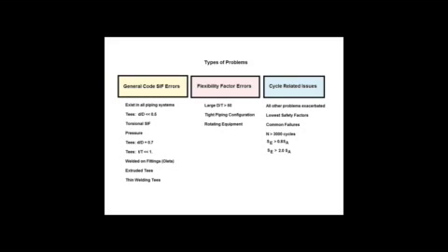For flexibility factors, we know that for all intersections and for all directions, the flexibility factors are not 1, as they're stated in 2012 and earlier B31 codes today for intersections. So we can definitely provide more applicable data for branch connection flexibility factors. Those will become more important as the D over T gets bigger.